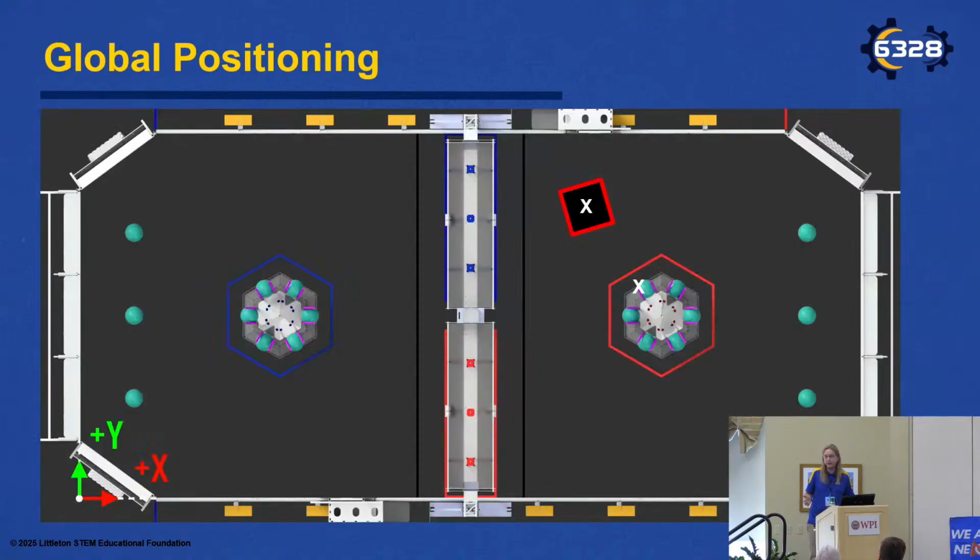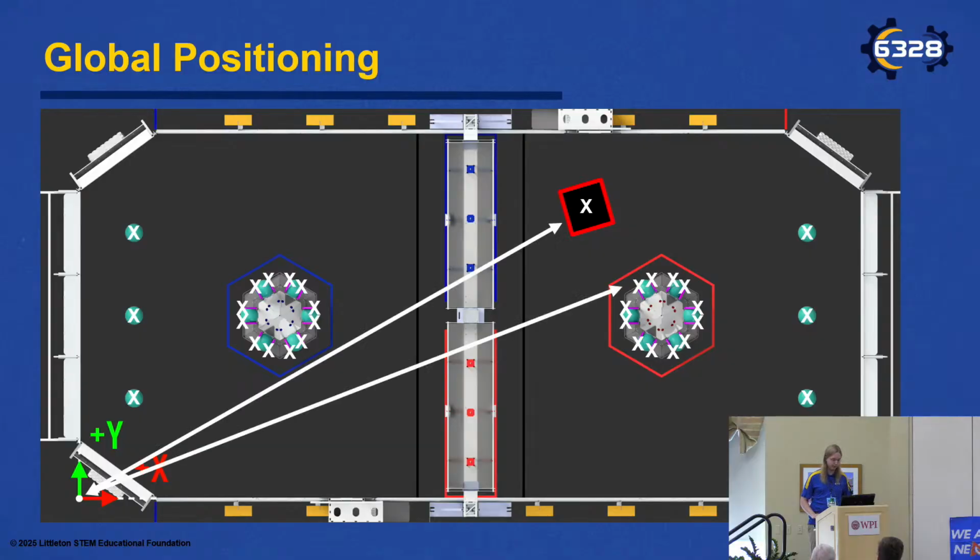Now, at first glance, it seems like global positioning would be fairly similar. We can plot the location of the robot and a target like this. You can see a branch there. But how are we representing those positions? Well, we're using a global coordinate system, which is represented by those axes in the lower left corner. And we can represent any position on the screen using that coordinate system. Each pose here is represented with a transform from the origin to the pose.